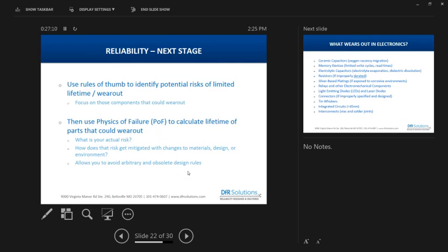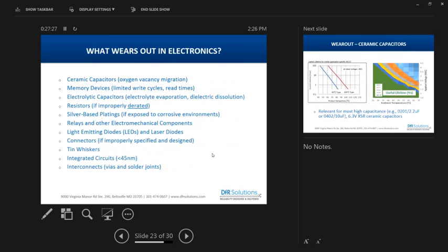If you have a very harsh temperature environment, you may have to mitigate that somehow. You may have to corner stake. You may have to underfill your BGA, that type of thing.